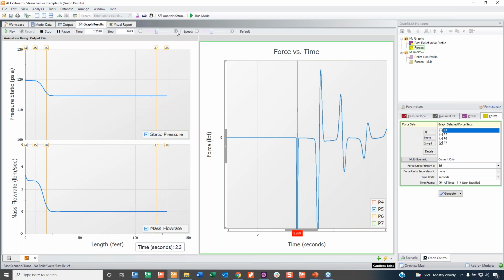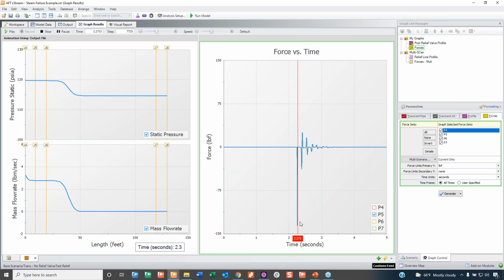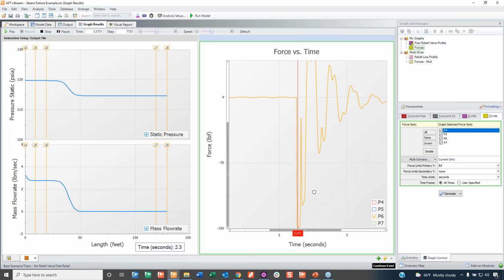So if we keep moving forward and look at my very big pipe, number one is you're not just going to see it so short-lived. It's not going to be just a blip and go back down. It's going to be extended because that wavefront is fitting in there this whole time. So what you'll see here is a much longer, again, longer being relative because we're still on the order of milliseconds, but a much longer sustained force, and then it comes back really quickly because it's right at that boundary condition, it comes back.